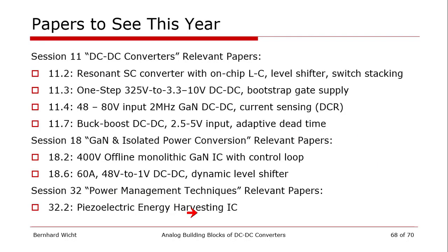I also would like to highlight some of the talks that we see at this year's ISSCC. We actually got 3 sessions on DC-DC and power management. In session 11 on Tuesday, we have a resonant SC converter, so it's a switch cap converter, but it has L and C fully integrated on chip with some interesting level shift and switch stacking design.